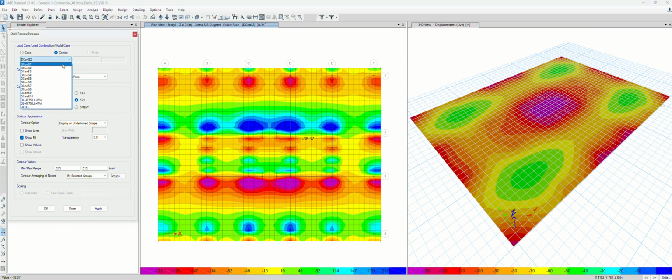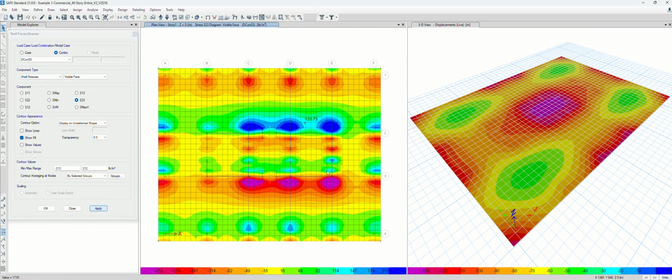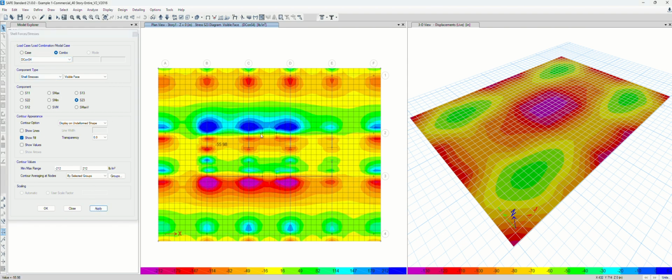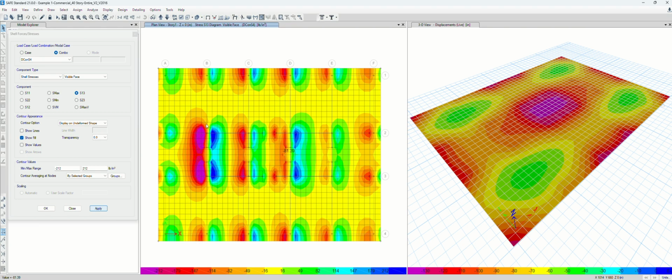If you want, you need to check all this shear stress for the combination, gravity and lateral load combined load combination. Same thing as 3, as 4. So this is a different plus wind, minus wind type of thing. You see the location of shear stress depends on the wind blowing direction.